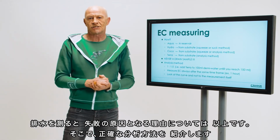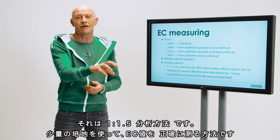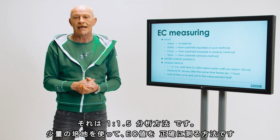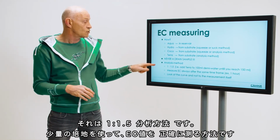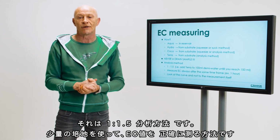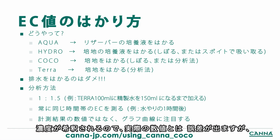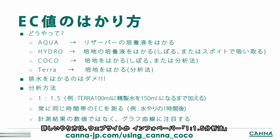If that is not possible, there is another analyze method. You take a little bit of the substrate and by an analyze of 1 to 1.5, you can measure the EC number. Of course, you did dilute it, so you don't have the real number. But in a PDF we put also on our web page, you can find how to make that analyze method.